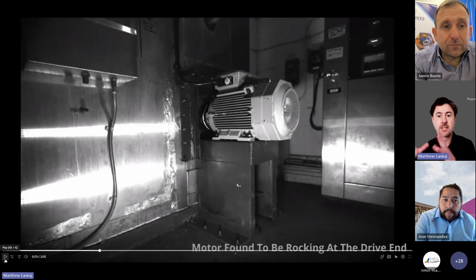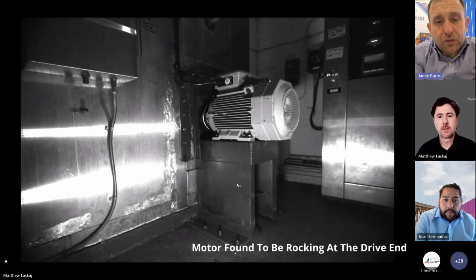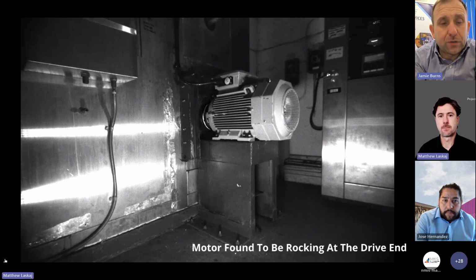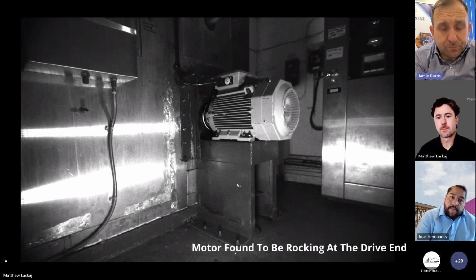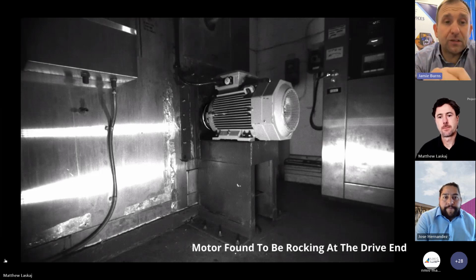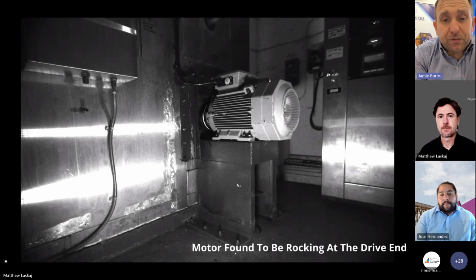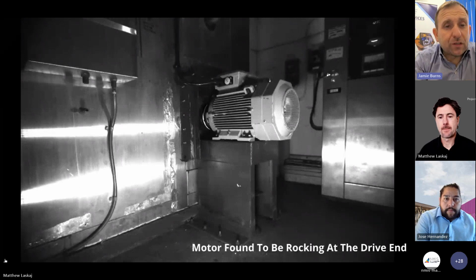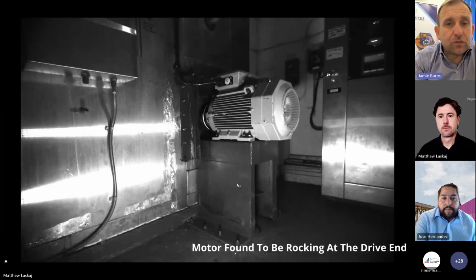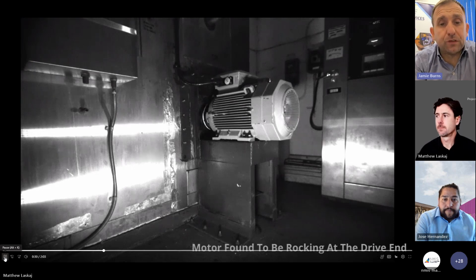So Jamie, you said motion amplification. So this is a video camera that you're setting up, isn't it, to actually record images of what's happening? Well, yeah. For anyone who's not heard of motion amplification before, it's a 2.3 megapixel camera, and each one of those pixels acts as a vibration sensor. So it takes this footage, puts it through some software, and then we can pick individual points anywhere within the picture and take vibration spectrums. Then the software puts it through a process and brings that movement to life. For us, it's been a key piece of technology, because not everybody understands a vibration spectrum. Not everyone understands orbital plots and all these kind of things. Everybody understands what a video shows you. So it's a very, very powerful tool, especially to prove or disprove that something is going on.